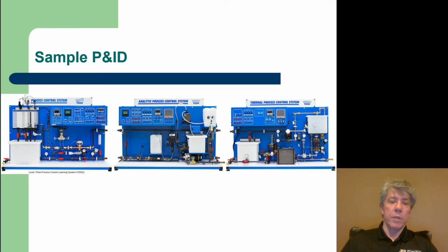And then you'll notice more to the right under the cabinet is a valve. It's a flow control valve. It's got a brass body and a dome at the top, sort of. That's the diaphragm that you can apply air pressure to and push the valve up and down, insert and remove the stem to control the valve and control the flow through it.